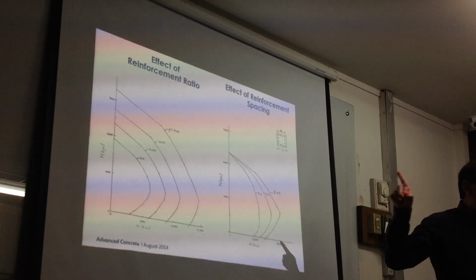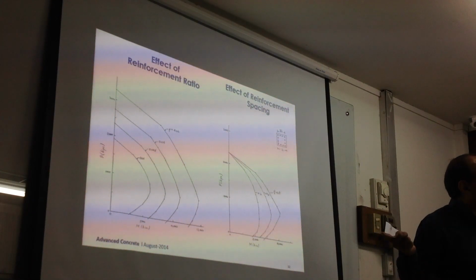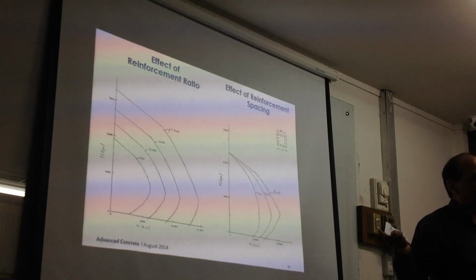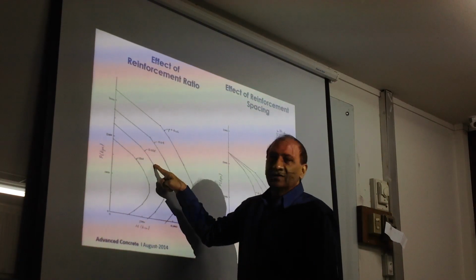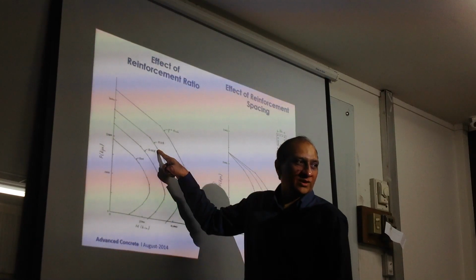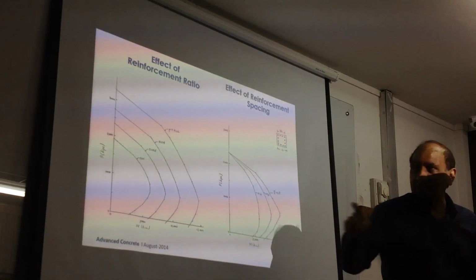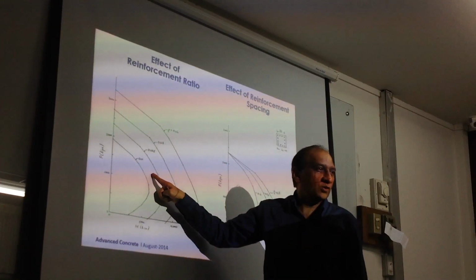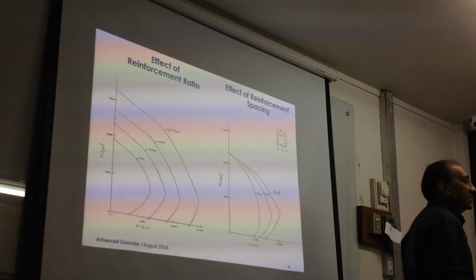So now you can use this not only for checking the DC ratio, but you can also use this to find out how much reinforcement you need, right? Suppose your point is here, you will provide that reinforcement. If your point is here, you will provide that reinforcement, correct? Next highest one, so that it is never outside the interaction curve. It is outside this curve, it is inside that curve, so you get that reinforcement. So this same curve becomes a design tool.